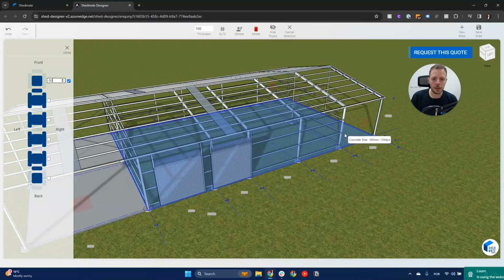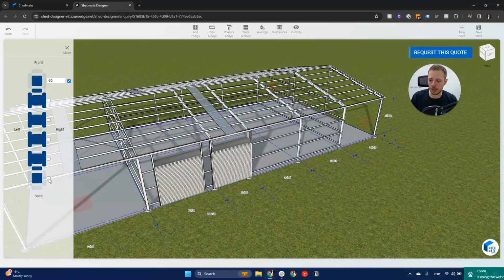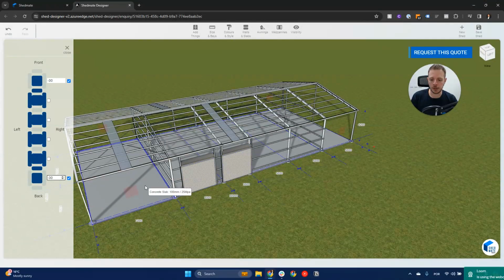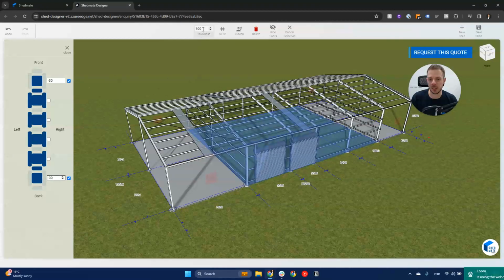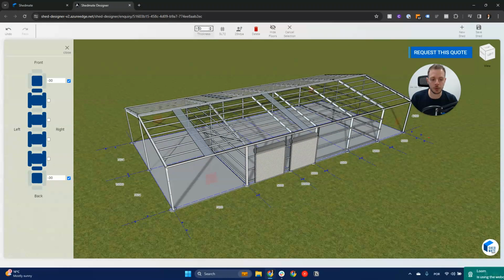And you can do that by just clicking here, and what it does is activate and break that concrete. So now I have a concrete slab here, here, and here. And note that the concrete modifications are the same. This is 100. If this one here is a thicker one, we could just say 150.